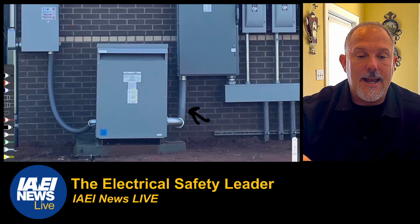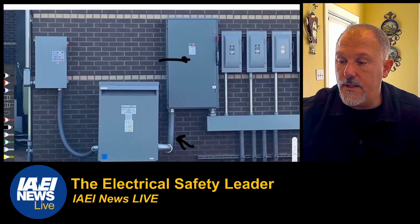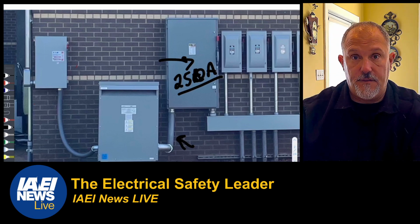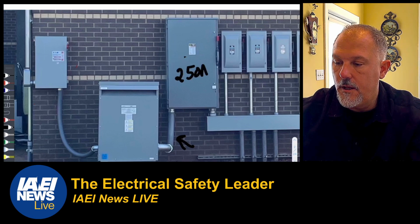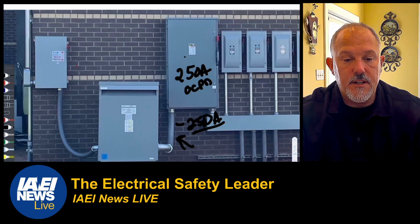The conductors terminate at a single circuit breaker or a single set of fuses that limit the load to the ampacity of the conductors. So we said this was going to be 250 amps worth of conductor. As long as the ampacity of those transformer secondary conductors equates to 250 amps, not less, then I am meeting it. We'll put 250 here: 250 amp fuse, OCPD, and 250 amps worth of conductor. So the conductors terminate at a single circuit breaker or a single set of fuses, so we meet that.